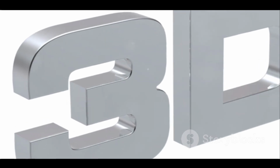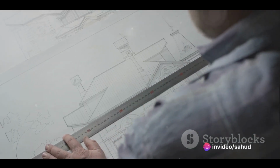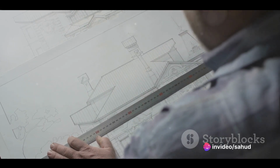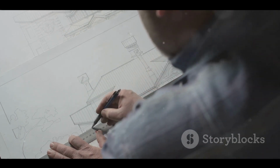Now let's add some precision to our sketch. We'll define the dimensions. Click on the Smart Dimension tool in the Sketch Command Manager. Then click on the line or circle you want to dimension. A dialog box will pop up. Here you can enter the exact length or diameter you want. Press Enter, and your sketch is now precisely sized.